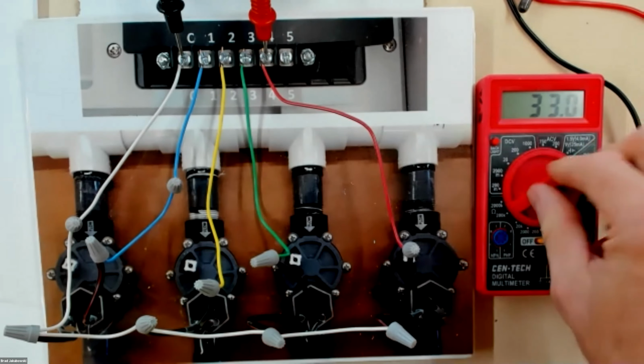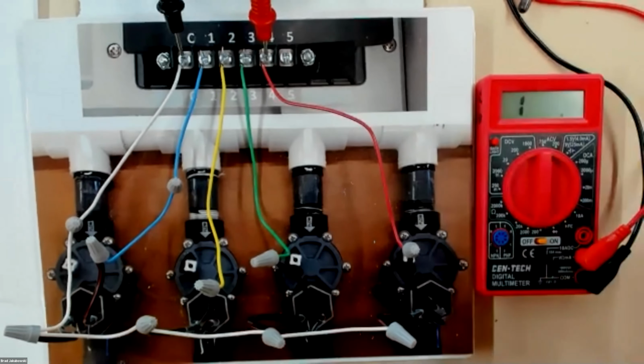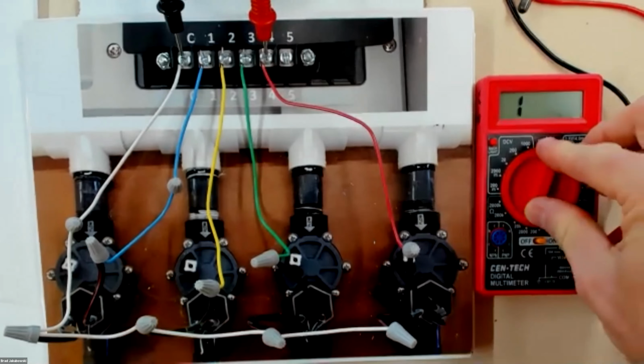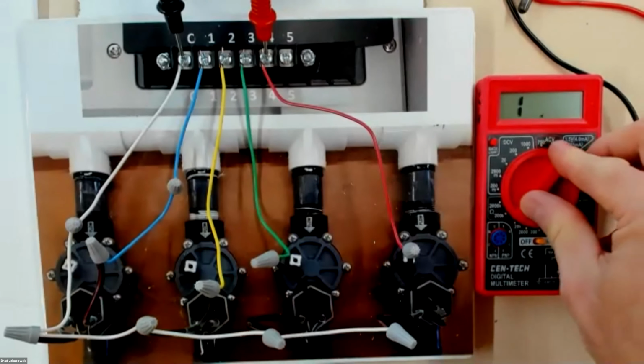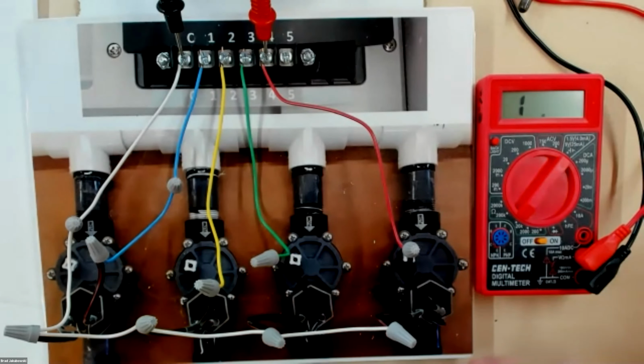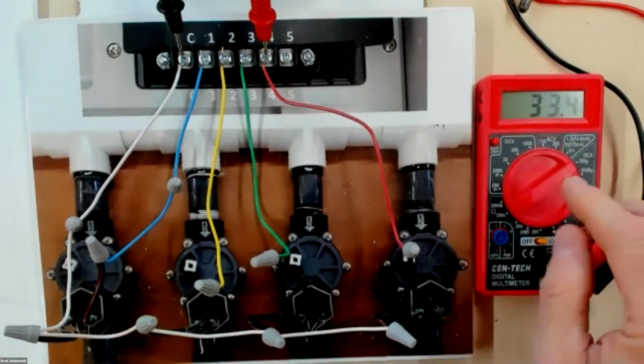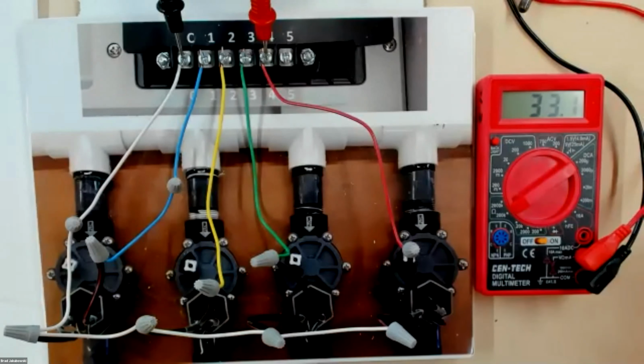To make them take an extra step and go from here, and it's like, well, does it give me a reading here? No, that's 0 to 2,000. Here's 0 to 20,000, still open. But then once I go to 0 to 200,000, aha, I've got a 33,000 ohm resistance reading here. And it may force you to ask questions.